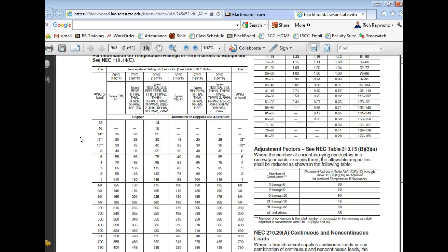Okay. And you can see as the heat rating of the insulator goes up, it allows us to conduct more current in the wire. Does that make sense? Okay. So we start off, if we use a TW insulator or a jacket, then we'll fuse it. Our overcurrent protection device would be rated at what? Didn't y'all get one? We're rated at what?